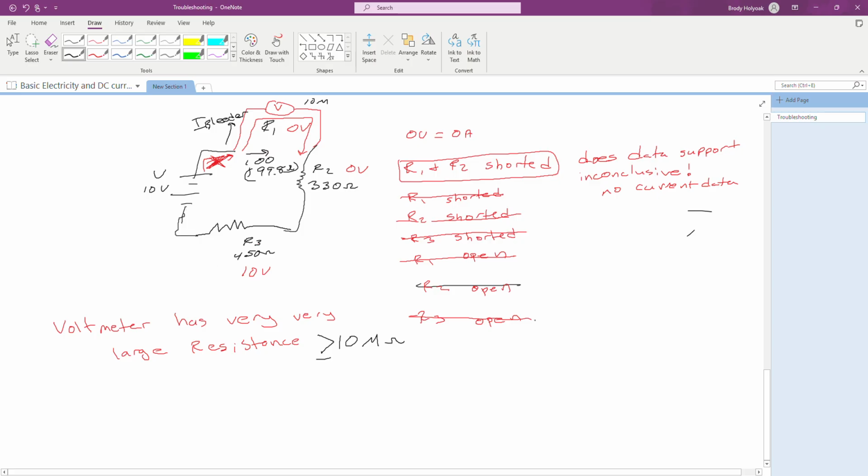So again, using the voltage divider rule, the voltage of R1 when it is open is essentially the resistance of my meter over my R total in series, times the voltage applied, V in. So my meter is 10K.